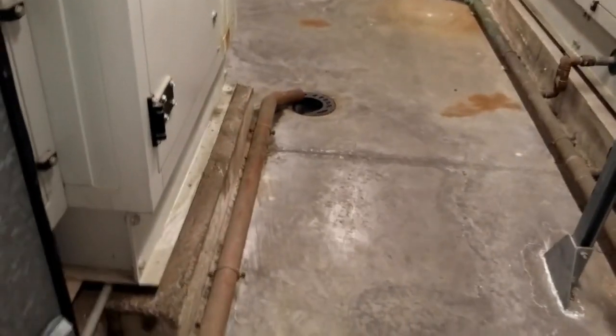And here's another example. So in the base of the AHU, you've got this drain here, and that will just collect up all the moisture that comes away from that. And in the peak of summer, that can actually be quite a flow rate, where all the water is condensing out of the air, and that is then channeled and goes off back to drain.